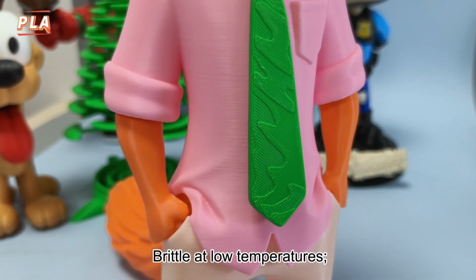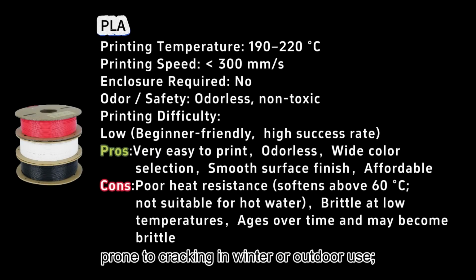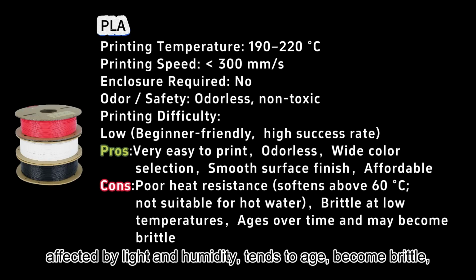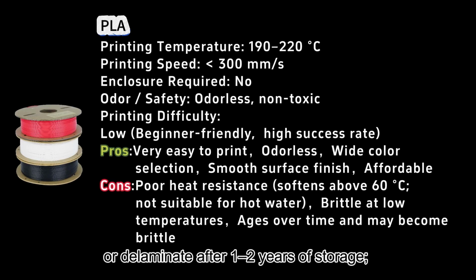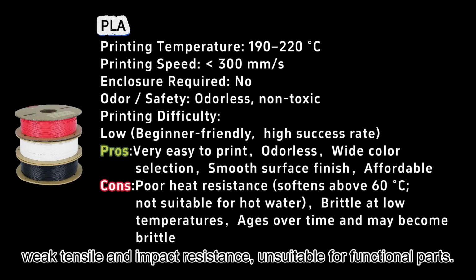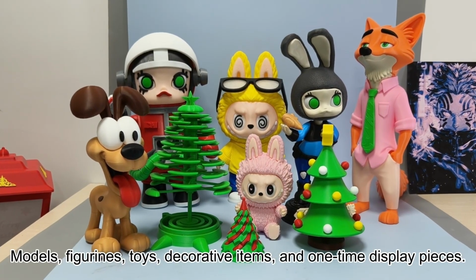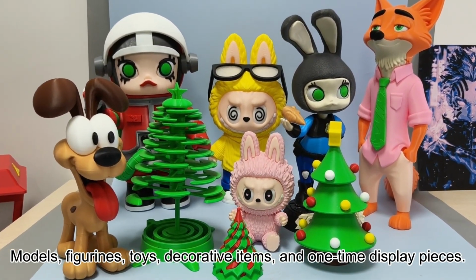Brittle at low temperatures, prone to cracking in winter or outdoor use. Limited long-term stability, affected by light and humidity, tends to age, become brittle, or delaminate after 1 to 2 years of storage. Low mechanical strength, weak tensile and impact resistance, unsuitable for functional parts. Applications: models, figurines, toys, decorative items, and one-time display pieces.